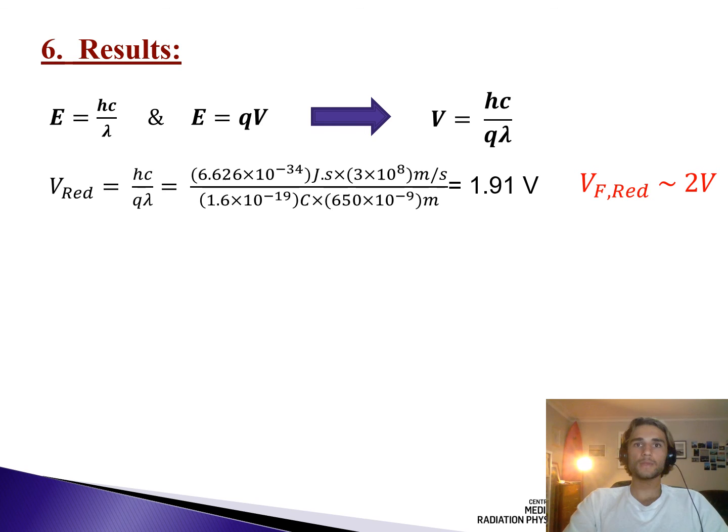If the polarity of the diode used in this experiment was switched, the IV curve would have the same shape, but be flipped laterally, since the anode and cathode will switch sides. Since the source voltage is AC, it will essentially have the same effect on the overall circuit.